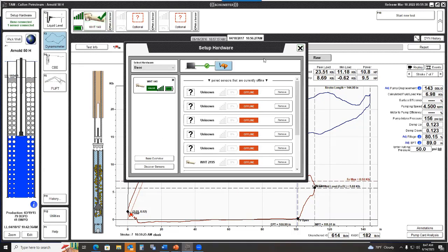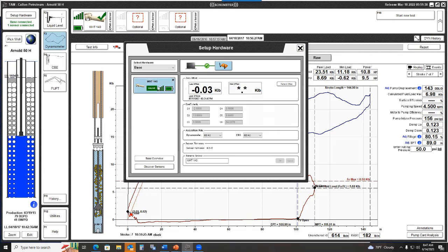okay, now I've got the ability to take a 0 offset on this particular sensor with no load on it. And so what I'm going to do is I'm going to go over to Perform Offset. There's no load on the sensor, and I'm going to click Perform Offset. Now you can see in this particular offset, the base in my office is we've got about a 30-pound offset that will be our new base to lock in. So once I'm satisfied with the offset, I'm going to go up and I'm going to click on Use Shown Value. And that's going to lock in that 0 offset. And now I can utilize the sensor.